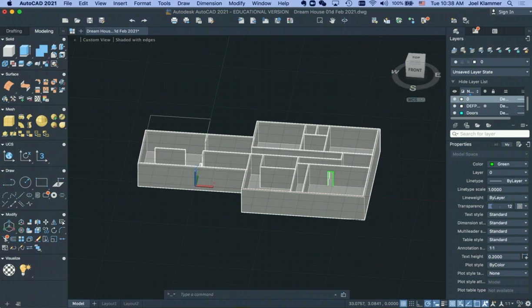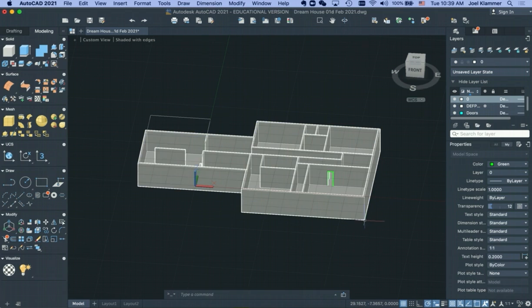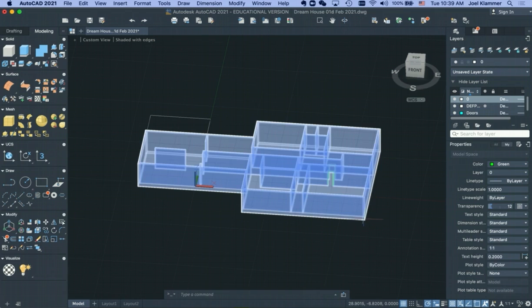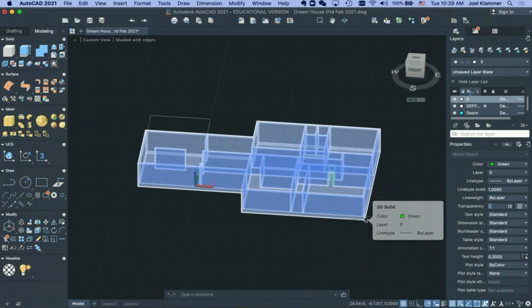Windows are a little bit more challenging because you don't want to do them actually from the wall up. And it's especially difficult with the exterior ones. Make sure when you're working with the exterior ones, if you work from this point down here, this point at the corner here, remember that's the bottom of your foundation. So don't forget the 1/2 meter up, plus then how far you want to go up here. The same thing with doors on this one. You need to actually work upward and then over.